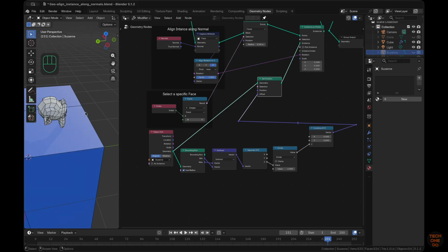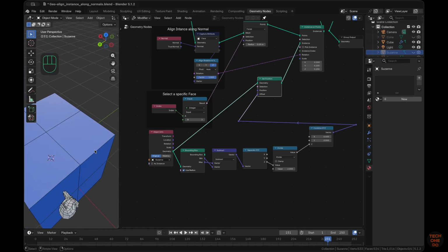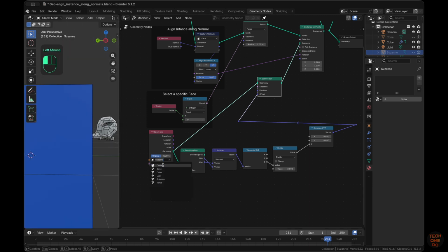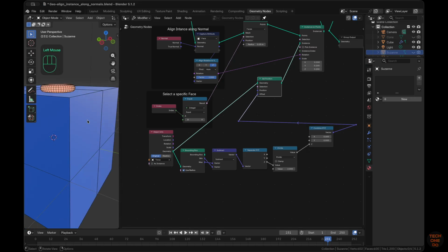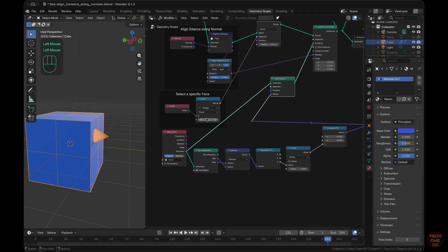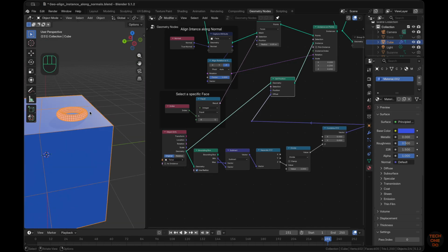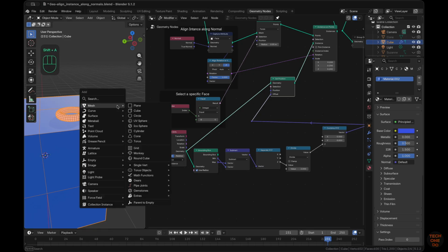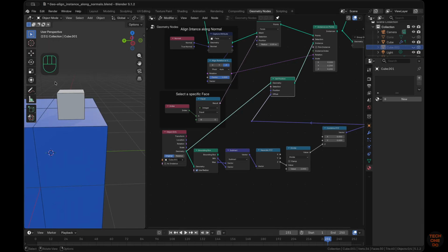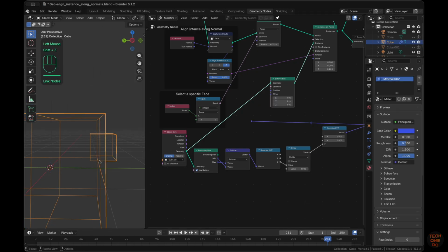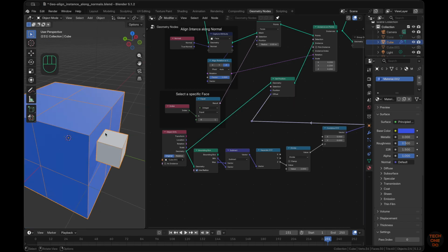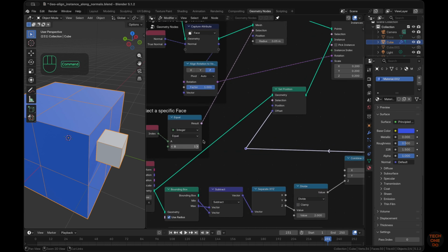Select a different face on the source object. Check with different objects. Let's also check how a cube would be placed. Press Shift plus A and select Cube in 3D viewport. Hide the new cube in Outliner and select it in Object Info node. Disconnecting the offset input shows how the cube is half submerged. Reconnect the offset property. It works as expected with different geometry types.